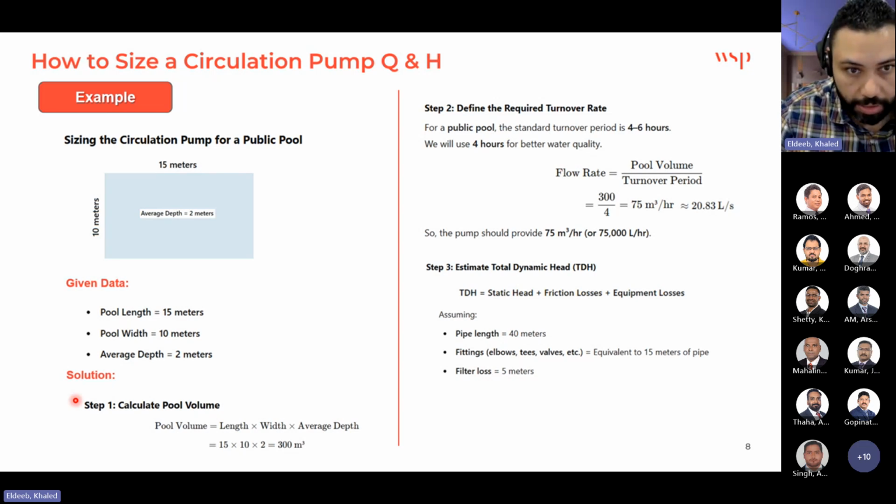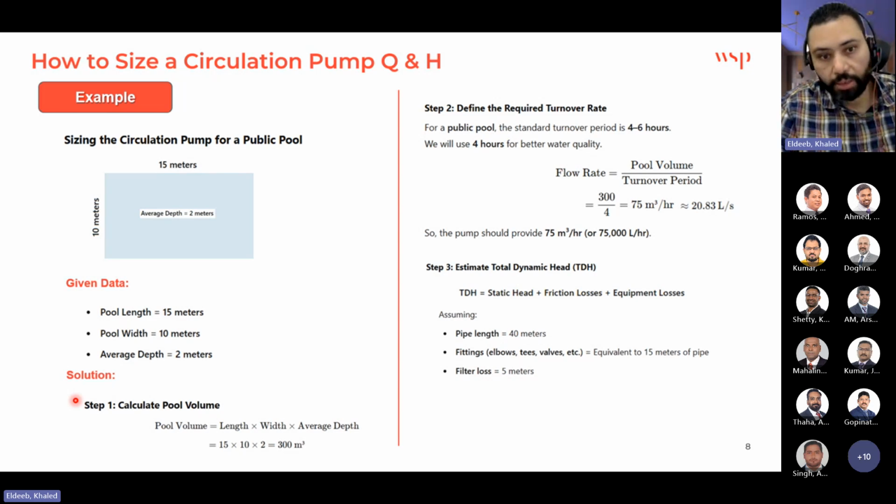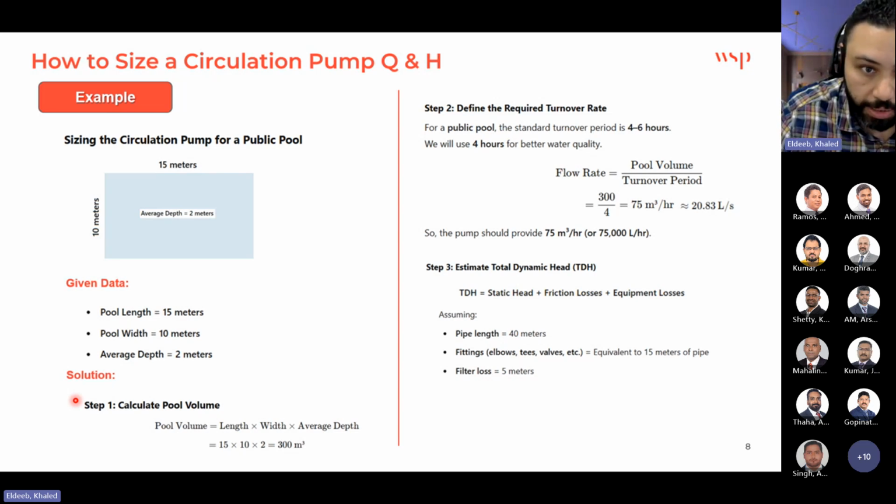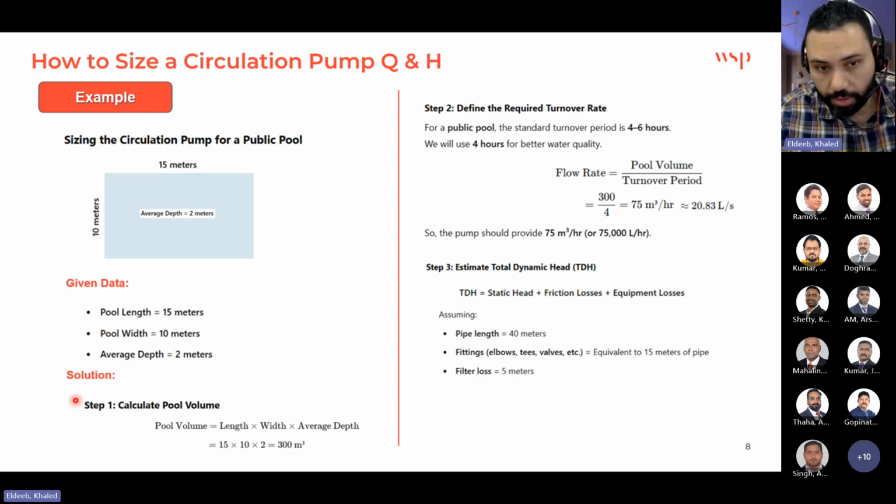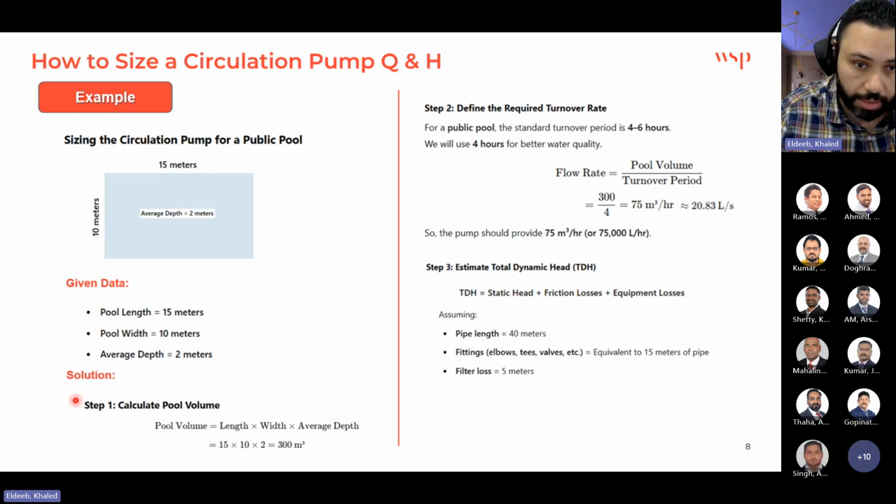You see here, this chart, we use it to calculate the friction in any system. I extracted this from the International Plumbing Code, and this is in English units, not in SI units. So they are using GPM, feet, and so on. So in order to calculate the pressure drop accurately, you can use this chart.